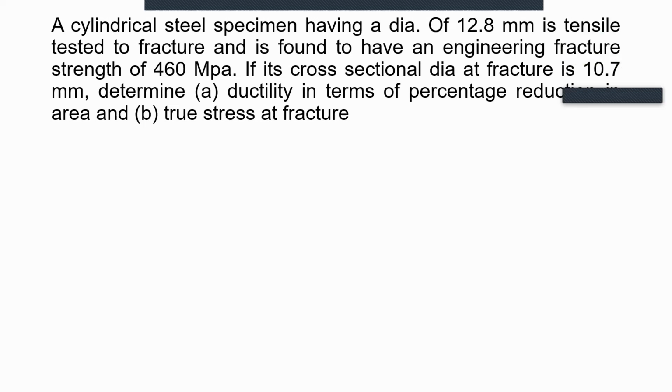True stress strain. Okay, so can we directly measure true stress strain from experiments? No, so that has to be found out theoretically. We can find out engineering stress strain, and from that, there are relations developed for determining the true stress strain values.